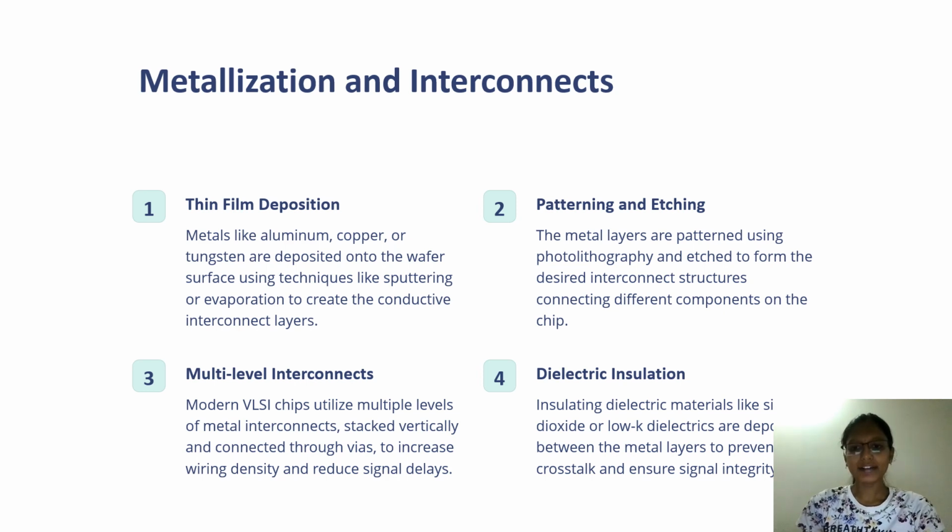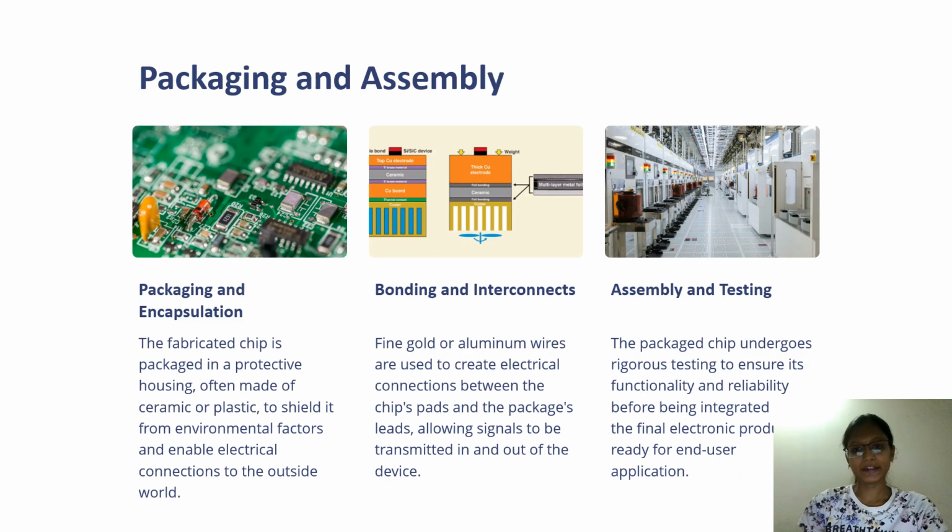Then I have dielectric insulation. Insulating and dielectric materials like silicon dioxide or low-k dielectrics are deposited between the metal layers to prevent crosstalk and ensure signal integrity.